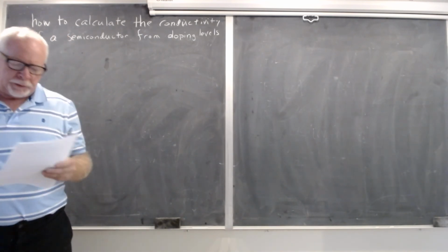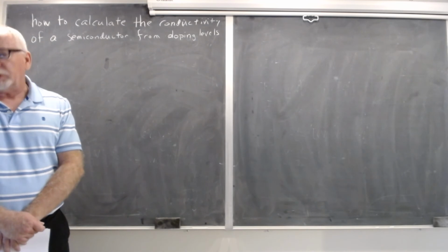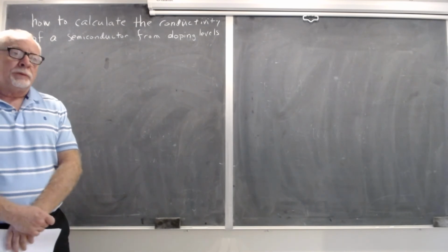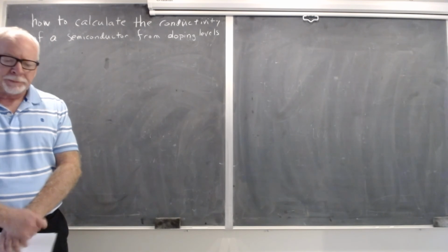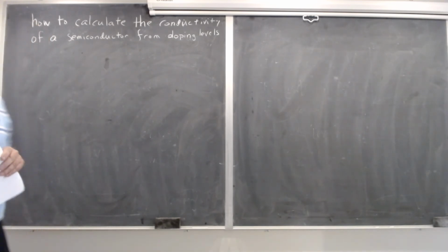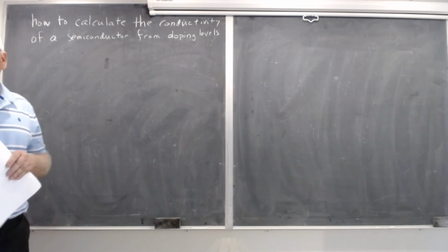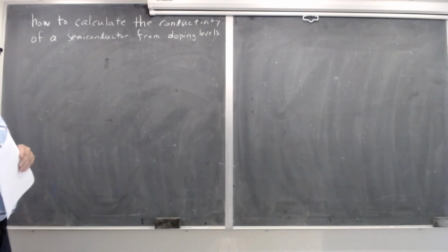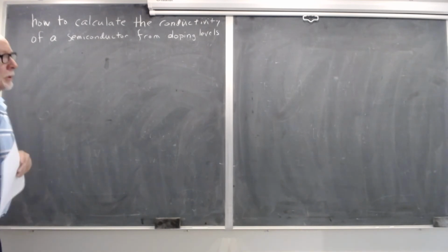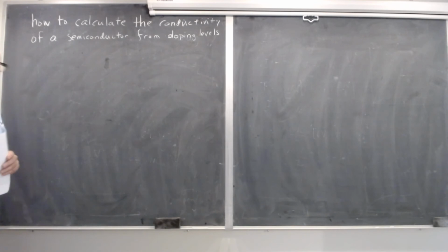The point being, if you go online somewhere, for example Virginia Semiconductor, and you buy a silicon wafer, it'll come quoted as having a certain conductivity or resistivity, like 1 ohm centimeter or something like that. Conversely, if you're going to fabricate a diode in that wafer through diffusion, you have to understand, when it was quoted to have that conductivity or resistivity, what the doping is.